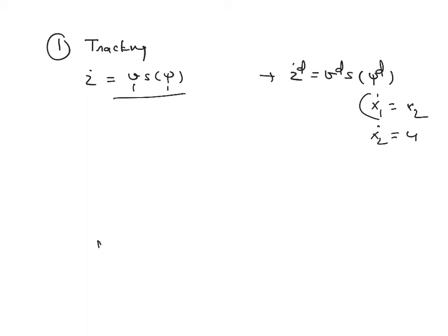So the simplest idea is, what if we consider, like in dynamic inversion, if you remember, we used to consider that the whole nonlinear thing is some input. First you solve for that input, and then you do inverse mapping to solve for V and psi. You remember the quadrotor trajectory where you had all the sine theta, cos theta terms, but you said, okay, the whole of this thing is some u. So the equation becomes linear. We can say that this is the input also, right? So what should this be such that z goes to z desired? We can first do that, step one, tracking.